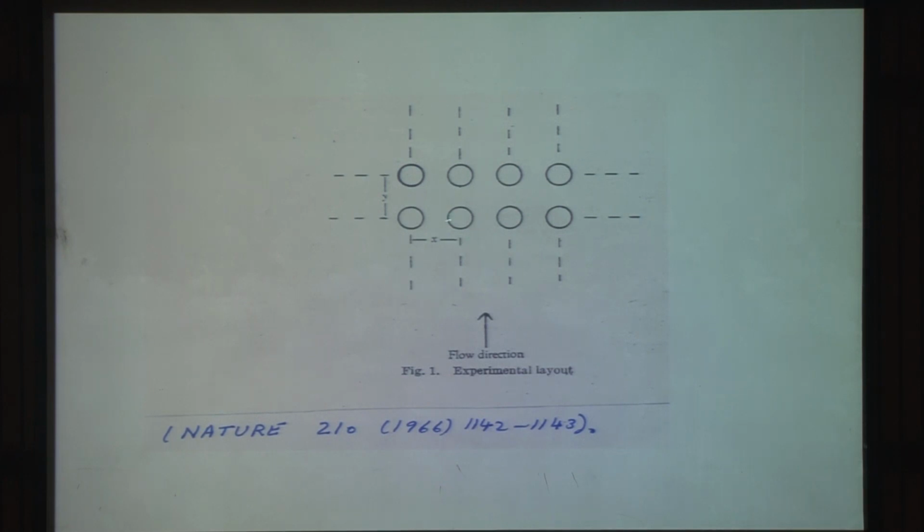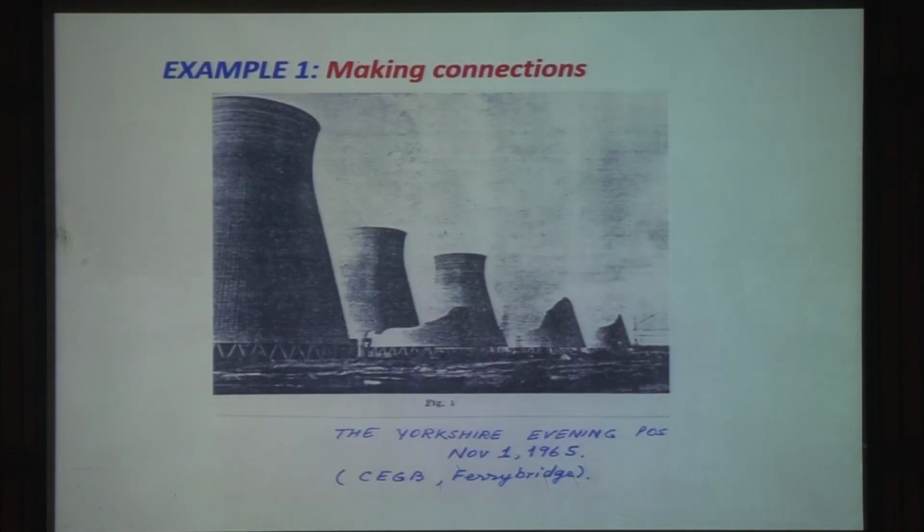And he found that when the gap was just of the order of 1 diameter, and actually those towers had a gap of less than a diameter, so this effect would have been even much more severe. And second factor was because, you see, if the air is coming from this side, part of the area is blocked by these towers. So the effective velocity impinging on the rear side of the towers is much more than the free stream velocity. So that was the main factor.